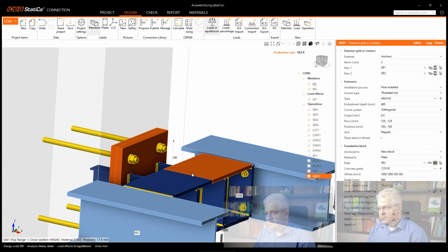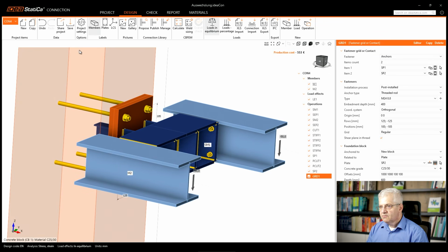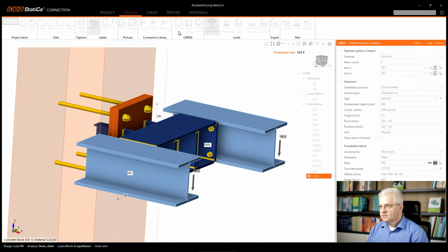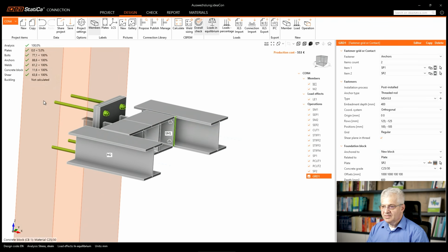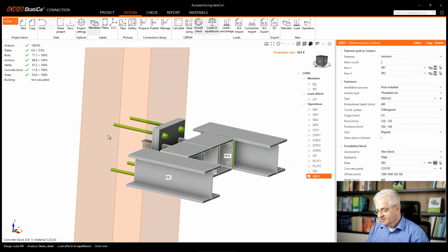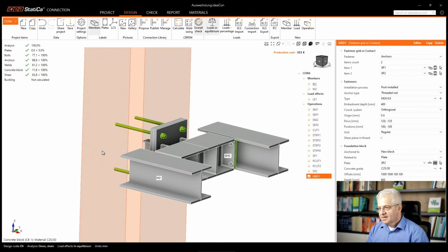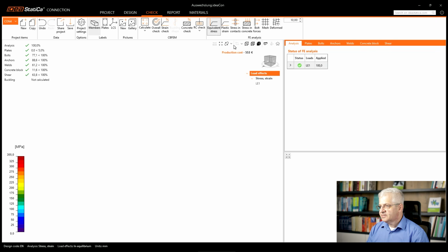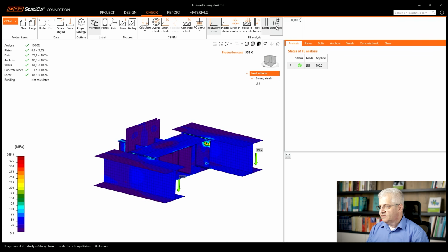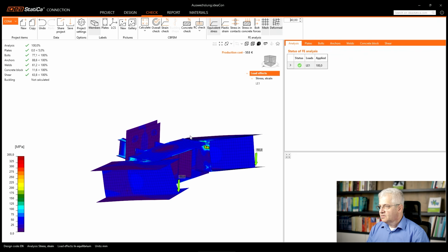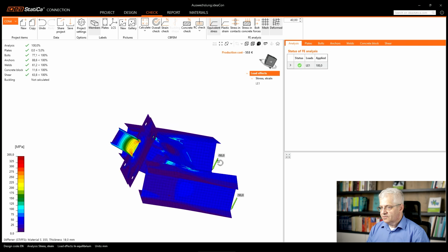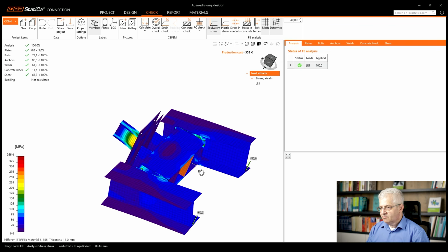Okay, everything is done. We can save and run the calculation and look if we get some instability or some another message. So everything is okay. Of course, I have prepared it. And we can check the, let's say, the stresses with mesh, with deformed, and you can scale the deformations, for example, with 40. So then you see the deformation.